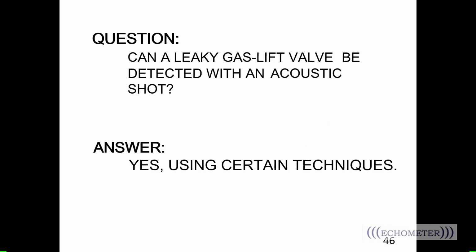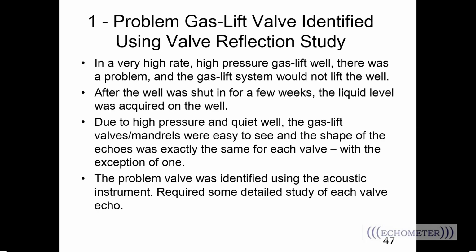All right, can a leaky gas lift valve be detected with an acoustic shot? For a long time, our answer was basically no, but we've learned some new things, and so now we say yes using certain techniques. So I've got 3 different techniques that we've used. This first one here was one that Lynn Rowland did. This was a very high rate, high pressure gas lift well.